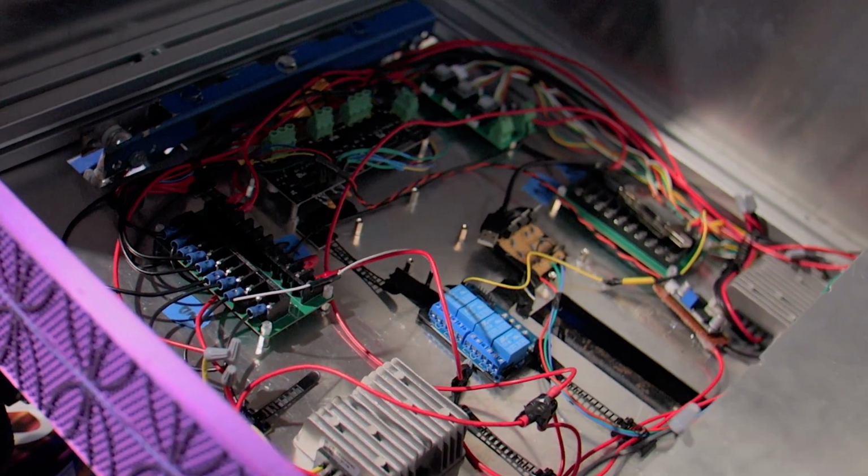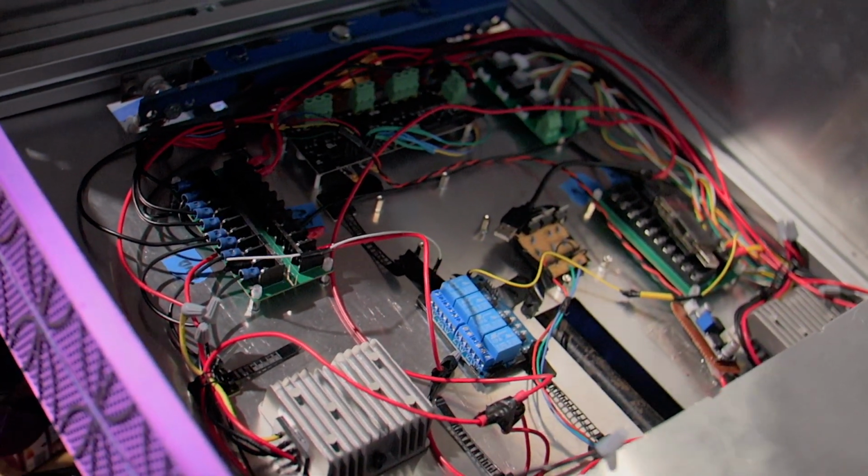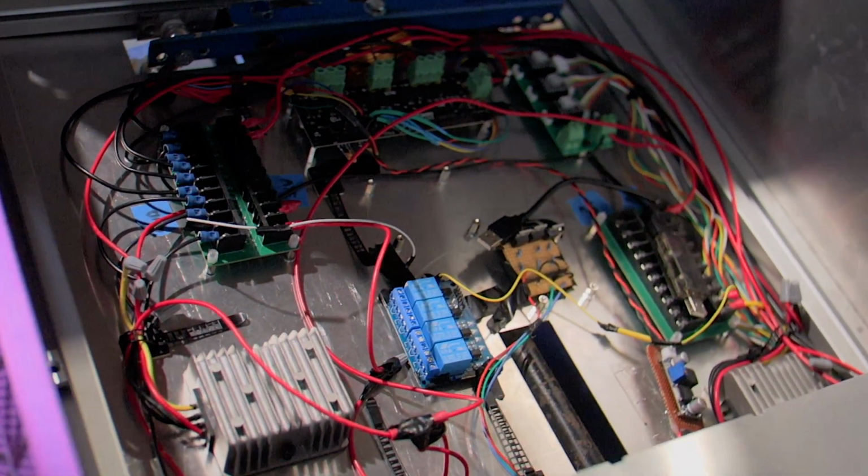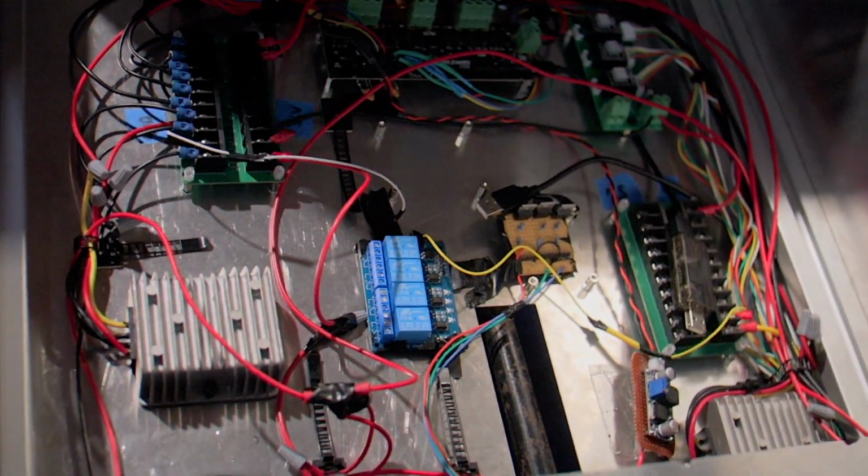When designing the power system, we considered the impact of ground loops and ground noise. We addressed these with the use of USB isolators on sensitive electronics, grounding topology similar to star grounding, and a brake resistor for our brushless DC motor driver to protect it from power generated by the motor during deceleration.